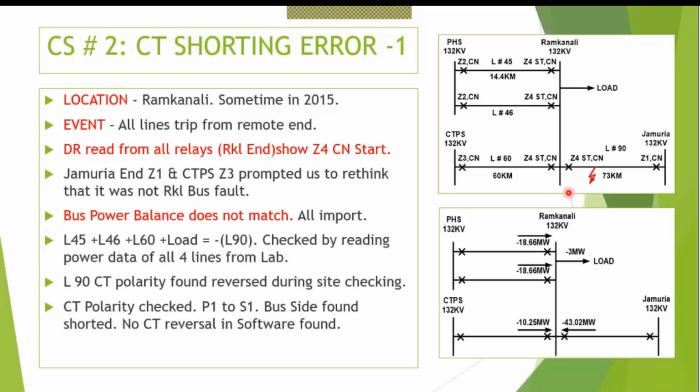But before we checked the CT polarity, what we did was we performed a bus current balance. What is a bus current balance? We call this substation up and ask what is your bus power being shown by the SCADA or something like that. But what we did was we summed up the megawatts of the bus. So the active power has to balance in a bus, otherwise it won't work. Reactive power can be either. Active power has to balance.